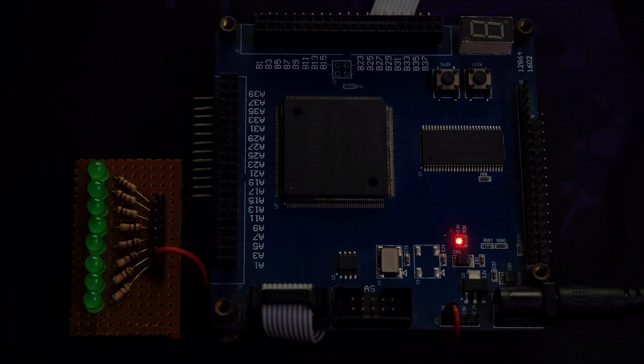Okay, so this was our 1 second PWM signal with 50% duty cycle, and that is working perfectly fine for this project. So that was our project. We have created a PWM signal of 1 Hz cycle and with 50% duty cycle. And we have used a 50 megahertz clock frequency to drive this PWM signal. And at the output, our LED was blinking at a 1 second cycle with 50% duty cycle. That means for half a second it was turning on, and for another half second it was turning off. So that's how it works.